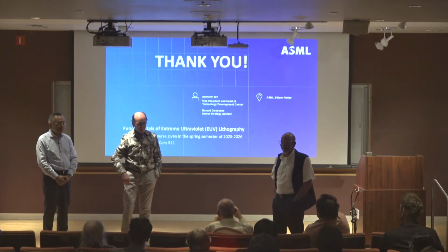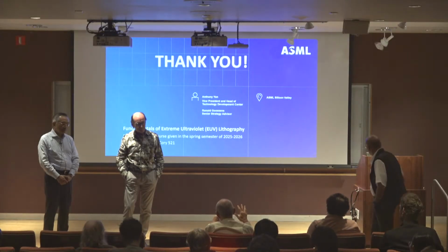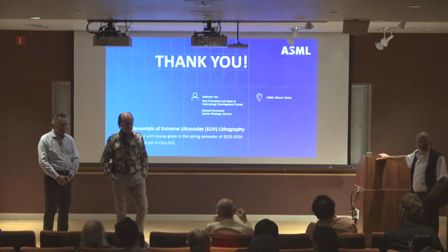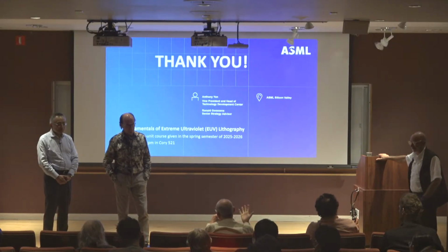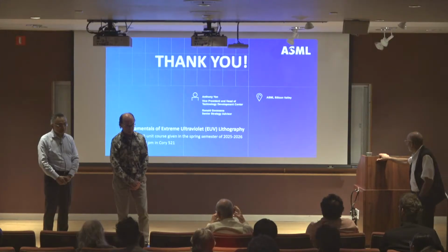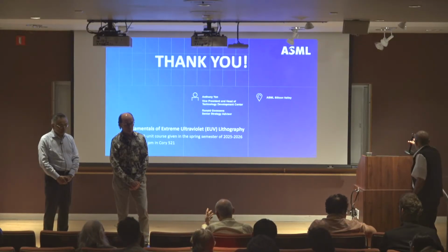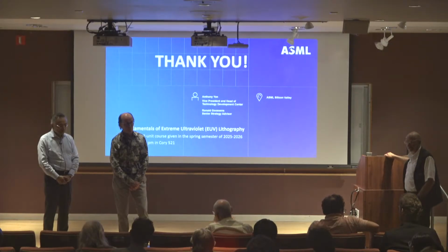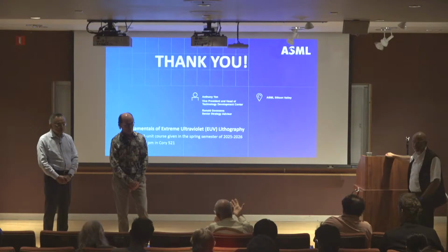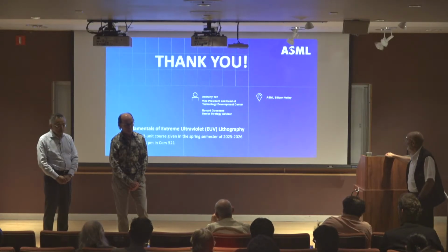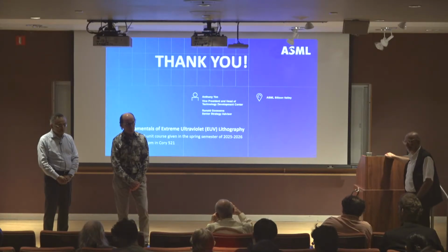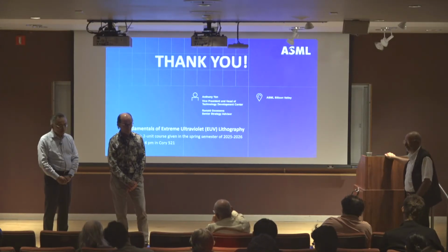Okay. So I'd like to ask a question about the optimization methods. One of the great challenges in optimization is if you have a great many variables to optimize, it gets really quite hard. Now, you spoke mostly about the source optimization, and there's a lot of variables in the source optimization. But then you also mentioned the so-called OPC, which is the mask optimization. And that adds even more variables, because in principle, the geometric shapes can be represented by an infinite number of variables. So you have a very huge number of variables. So shouldn't you be doing the co-optimization of all of them together, rather than saying, I'm going to do source optimization? You should be saying, I'm going to do the optimization of everything. The source, the mask, I do it all in one big optimization.